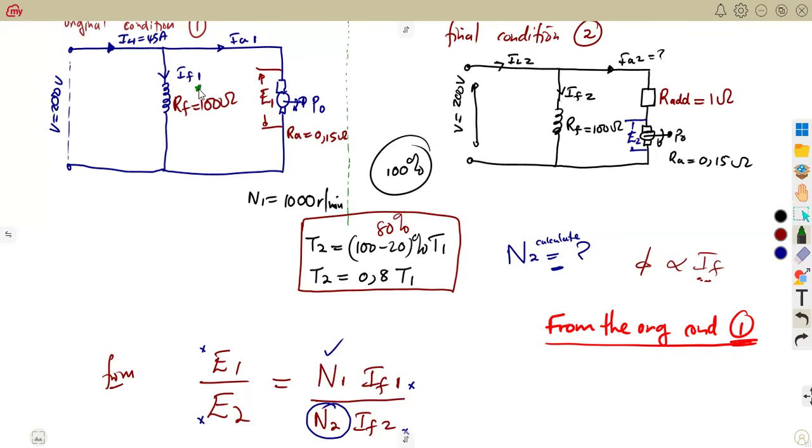So let's think about the field current. Let's go back to our N4. Remember in N4, under a shunt, I said the voltage here is the same, even if you check your electrotechnology. The terminal voltage there. So to calculate the field current is going to be easier, because we simply use voltage over that resistance.